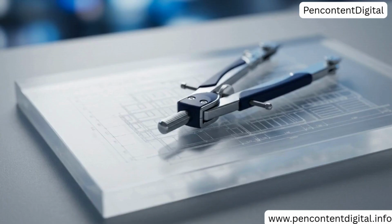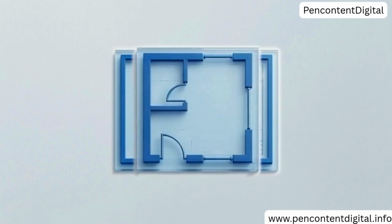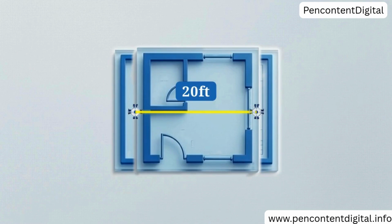With the text data extracted, the focus shifts to the physical geometry of the design. The software must assign a physical scale to the digital space. Look at this structural floor plan. By drawing a line between two known column grid lines and inputting their actual distance, the user completes the calibration process. This single measurement grounds the entire digital sheet in physical reality.